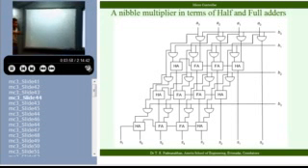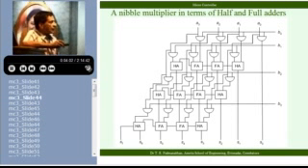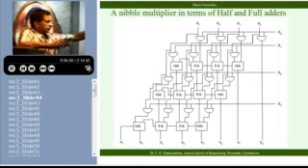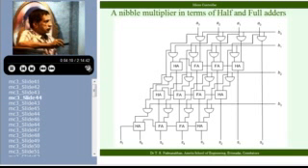It looks like a maze, but it's not very difficult to make out. See, all that I have done is an exact correspondence between what I have shown here and the table earlier. Here I have A0, A1, A2, A3. I have taken B0, and I just put an AND gate. That's all I have to do. For multiplication, I just put an AND gate.